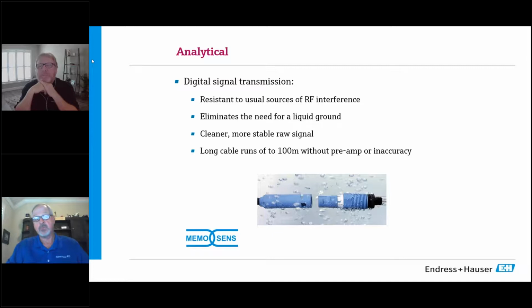So if you have an EPA required calibration or something like that, then all you'll have to do now is download out of that software, say, here, this is everything we've calibrated, every pH probe every day. There you go. It takes away the requirement of storing that data, typing that data. You do the calibration on your laptop, on your notebook, whatever it is, through that little black box, and MemoBase will store that calibration history.